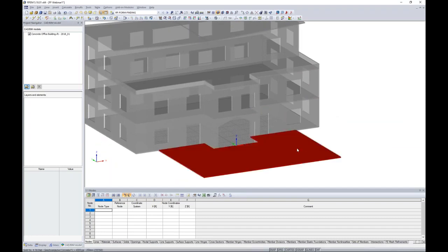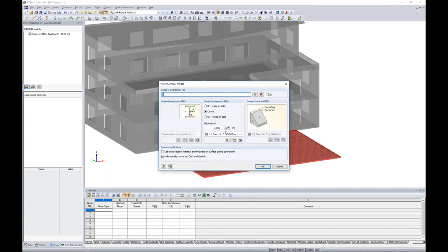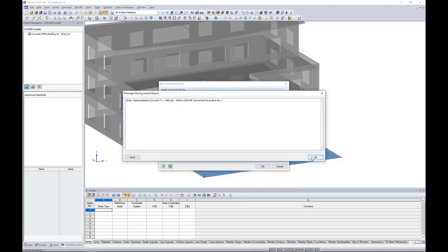So what I can do is to take one of these elements, and in particular, we'll start here with our front slab. I can right-click to create a surface. Now, the program generates some arbitrary thickness and selects some material within the model. This really doesn't matter. We're actually going to end up deleting this slab. We're purely using the nodes and lines for geometric purposes to generate our canopy structure. So I can just click OK.